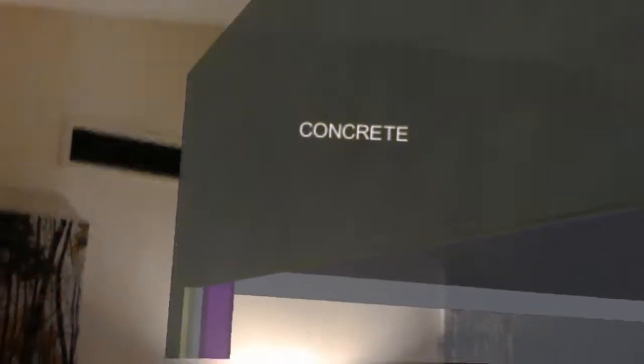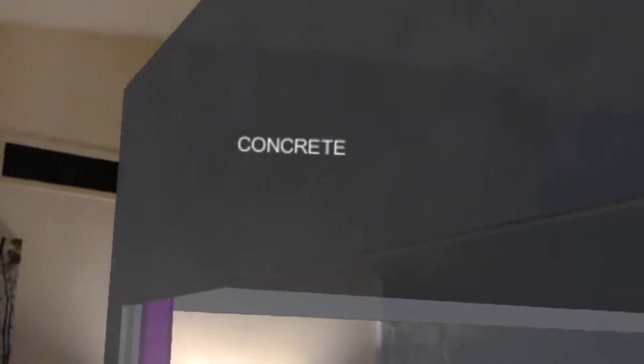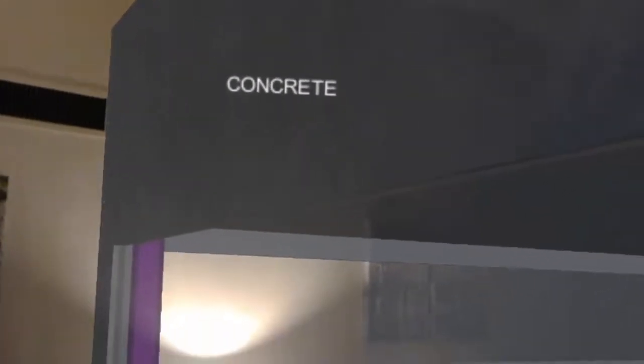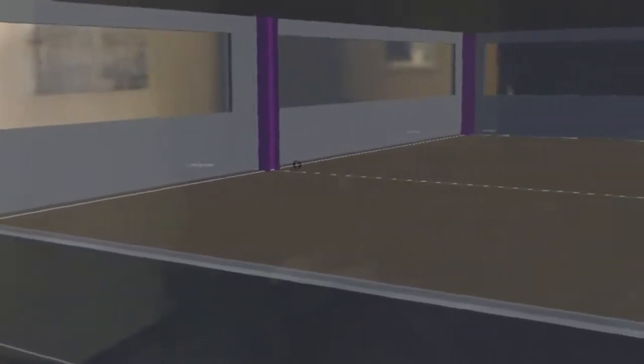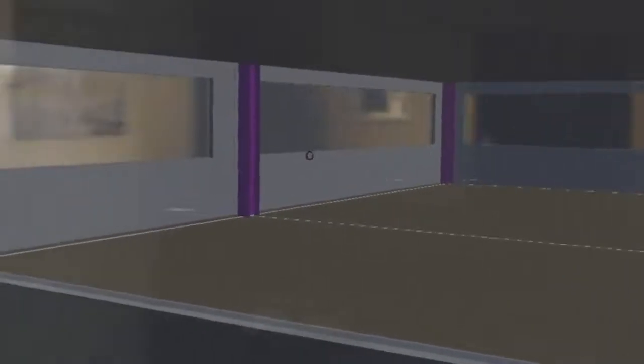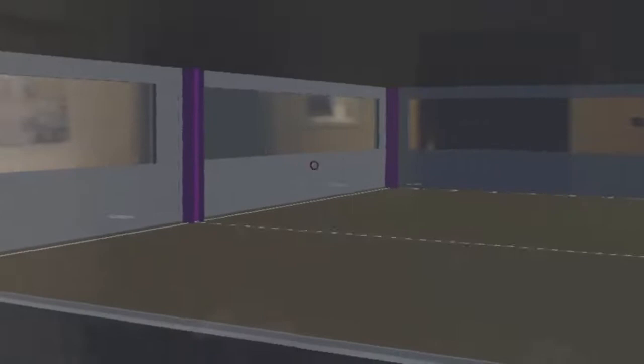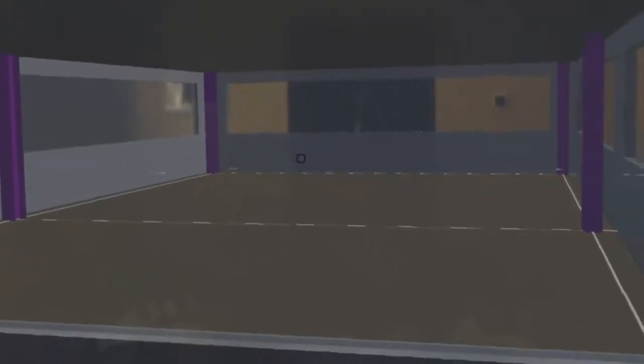Okay, I can just finger tap, and then that will show that selected object, and it'll either tell me the name of that object, or if it's steel, it'll actually give me the piece mark and profile. Now, what's great about this is by default you see materials and shaders here, and glass is transparent. The way this works is when I publish it from Tekla Structures, it reads the material type, and then it maps that automatically to the materials and shaders. So I'm not doing any of that manually. That's all automatic based on what I set inside of Tekla Structures.